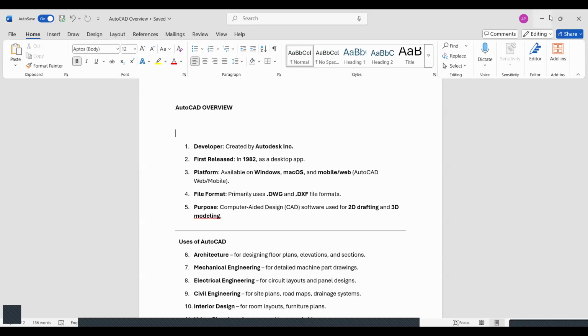This is how you need to control C and control V on it. Now what is this feature? Paste as original coordinate. Suppose we are opening a column plan, and these are the columns which need to be placed on the plan. So I'm just copying it with the help of Control C. Then I'm pasting it on my plan by right clicking on it, paste as original coordinate, or you can go here and provide this. But the easiest way is just to place it into original coordinate.